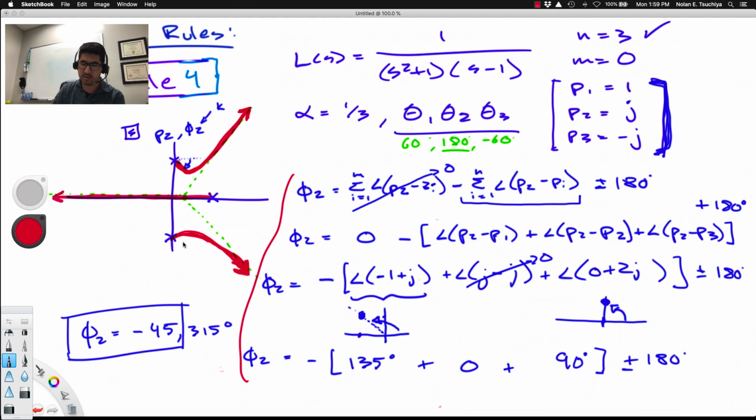However, every term on the final exam, at least a handful of students will complain that they could not finish because they ended up computing 6 or 7 departure and arrival angles when really they only needed to do 1 or 2. It's a very time-consuming process, especially in an exam situation where you have limited time. So Rule 4 is outlined here, but specifically, according to Rule 4, you should minimize the number of times that you apply that rule. All right.